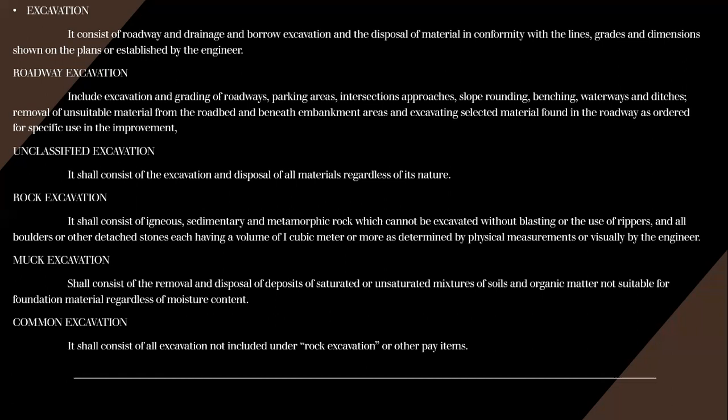And the next one is muck excavation, which shall consist of the removal and disposal of pieces of saturated or unsaturated mixtures of soil and organic matter not suitable for foundation material regardless of moisture content. Muck excavation is the wet soil, the muddy soil that needs to be removed, including clearing, so that we can build the roadway.